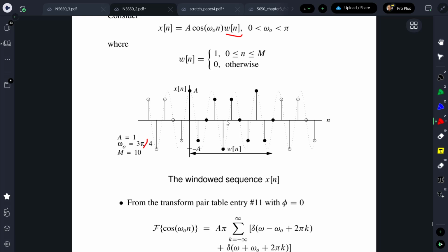But estimation theory is something that would take information and then estimate parameters related to some model that you're saying, this is what I think I have out there, but I don't know what the parameters are. The parameters could be magnitude or amplitude A, frequency omega naught, and a third variable would be the phase of the sinusoid, perhaps, depending upon the type of capture you're doing. So that's a good question, and that's what we're going to see, how well in the frequency domain we can assess what's really out there from this capture.